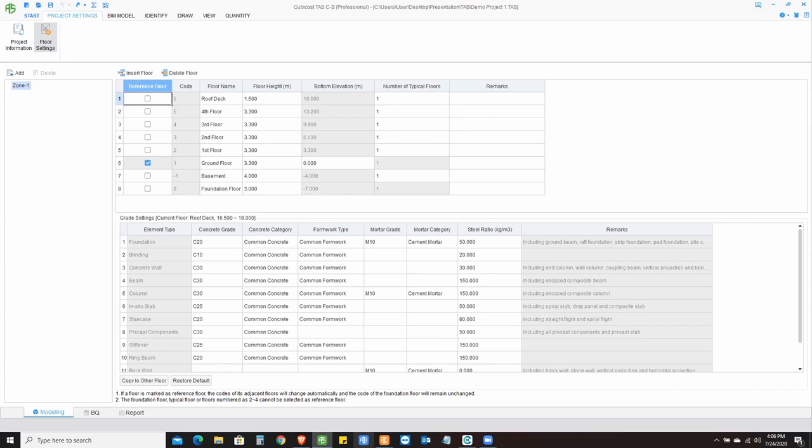Okay, so the next question here relates to reinforcement. How can we calculate exact quantity of reinforcement? Again, touching on that previous question from AJ. Okay, so it's pretty much a similar question. What I'm trying to say is that you can get an approximate estimation of steel quantity, right? If you really want to do that, you can go ahead with steel ratio.